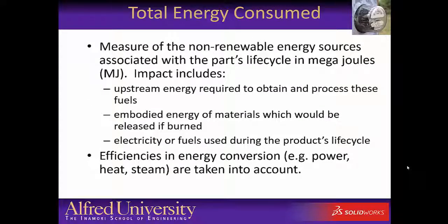Total energy consumed is a measure of the non-renewable energy sources associated with the part's life cycle. The impacts include the upstream energy required to obtain and process fuels that are non-renewable, for example, oil or coal, the embedded energy of materials which would be released if burned, so for example, if at the end of life you incinerate the material, there's a certain degree of energy associated with the material that needs to get taken up by the incinerator, and the electricity or fuels that are used during the product's life cycle.